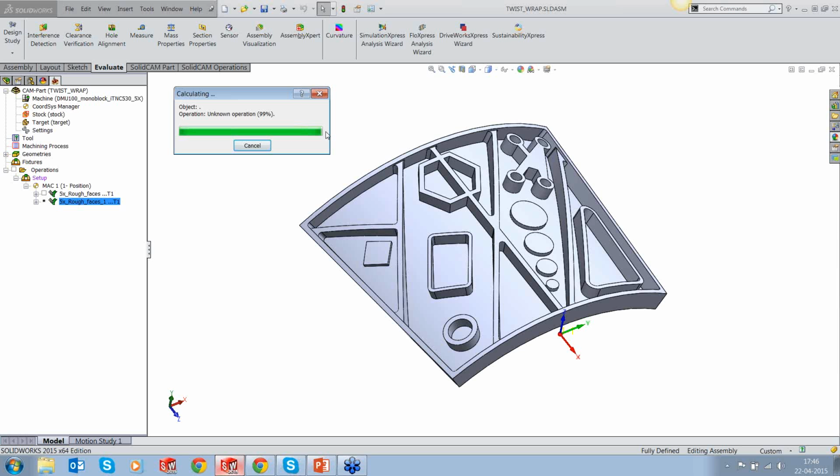Okay, so what it is basically going to do is provide me with a step over between 4 millimeters and 3.2, and it will adapt itself between those two step overs to create a toolpath which will spiral around. Let's say if it's doing the geometry here, then it will spiral around inside this rectangle.